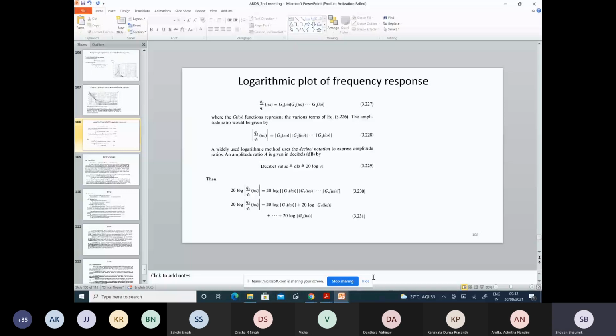Making a Lissajous figure is simple. The two signals you need to superimpose, and if you superimpose two signals, it will make a Lissajous figure. The Lissajous figure will be a kind of ellipse, and its axis will be at a different angle in xy coordinates. The ellipse does not always have its axes along x and y; it may have an axis at some angle theta with the x-axis, whatever it may be.